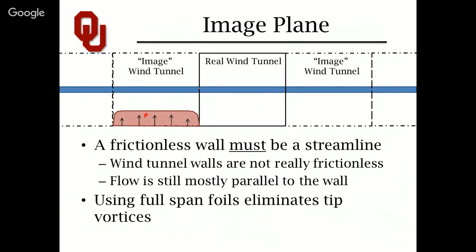But what happens in this scenario, what allows you to consider this as an infinite airfoil, is that the presence of a wall forces flow to always be tangent to it. I mean, air moves along the wall. That's not a surprise. It's a commonplace thing. You cannot pass air through a wall. So mathematically, if you wanted to express the presence of an airfoil in this environment, instead of trying to model the airfoil and these rigid surfaces all the way around it, you can simply put another section of the airfoil next to it.